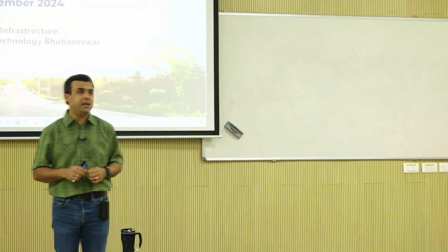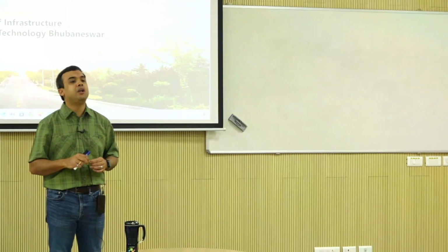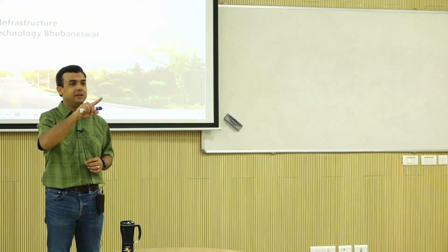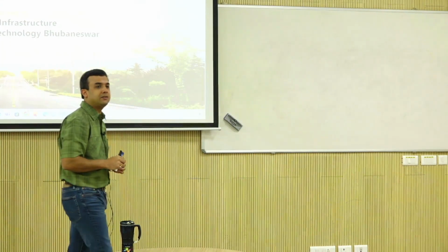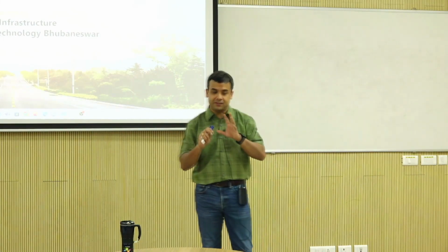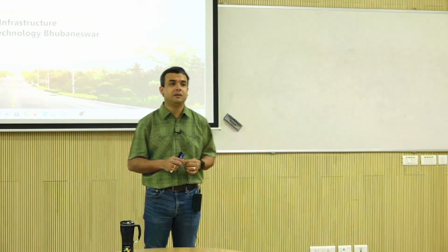So, modulus. All I can say is I have done FWD work on cold in-place recycling, cold mixes and stuff, and some modeling. I have not tested them for resilient modulus, but the modulus we used was 100,000 psi. If you want just one E value, it's about 100. A typical good quality aggregate was about 40. As I showed, 40, 45 is a very good quality aggregate. We used about 80 to 100. That's all I can say.